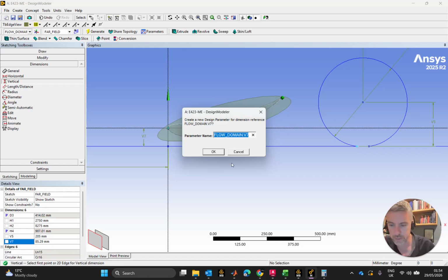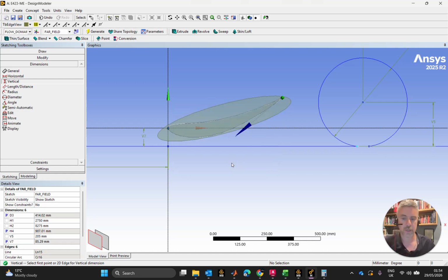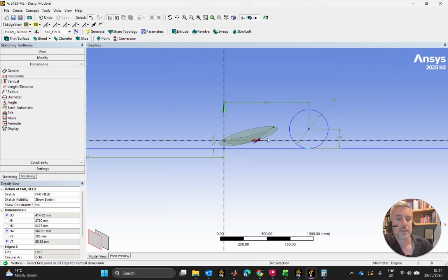So what I'm going to have here, I'm going to call this LE dot to track, leading edge to track height. And remember that. In fact, I'm going to create a new parameter and call it ride height. I'll put in a number, 42, 50, 30 mil, whatever it might be, and have that update everything from the design point table. So there we are.